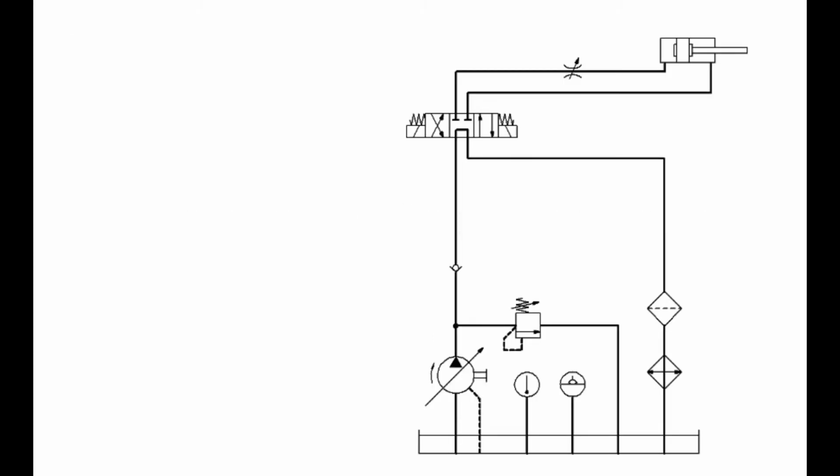In principle, our hydraulic circuit is already functional. In practice, however, a number of other components are necessary, with which we are still unfamiliar, and which cannot be classified in any of the three functional groups yet described. Components that cannot be classified in any of the three functional groups of a hydraulic system are called other accessories. Among these components are, for example, lines and line connections, hoses, union connectors, measuring and test equipment, and pressure accumulators.